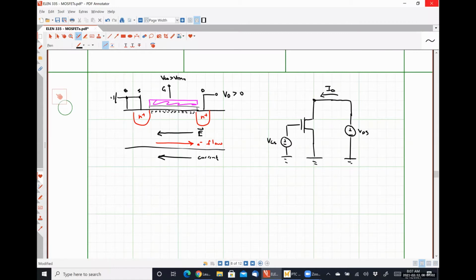We have this indicated direction of current flow, assuming the voltage VDS is positive. This is technically true even if VGS isn't greater than VTH, because we have something called sub-threshold current that's beyond the scope of this class. And I guess I should technically draw the arrow there to indicate which one is my source. And just to cover all the bases, gate, drain, and source terminals, where I'm assuming that my body is tied directly to my source, okay?